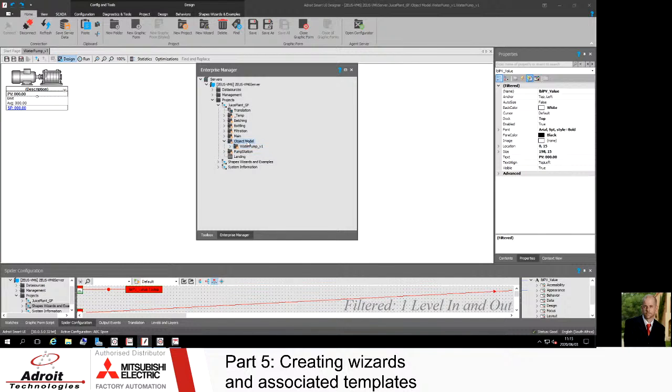So really what we're doing is I create a water pump. You'll notice that I've got a version number behind it. That means that if I come along and add a new type of VSD or new functionality to this particular object or piece of equipment, water pump, I can just increment my versioning, and I can still maintain equipment that runs on the older version with newer versions coming in. All right, so I've created that folder structure inside there.